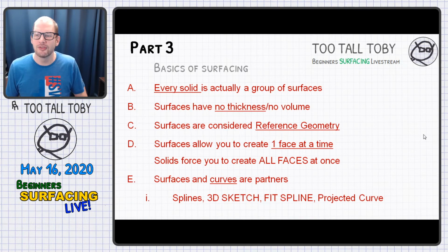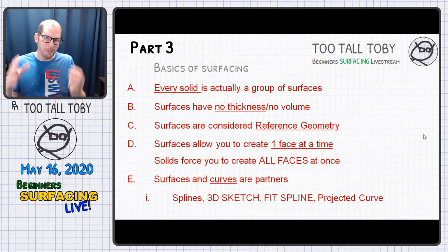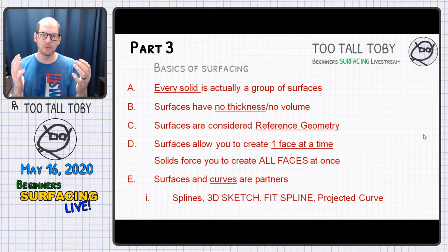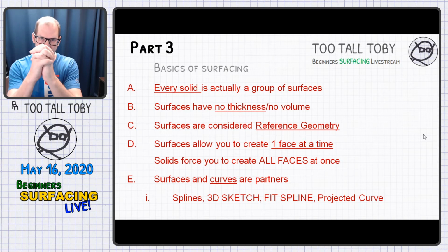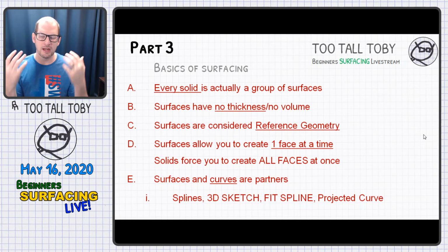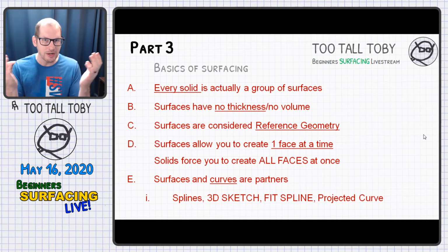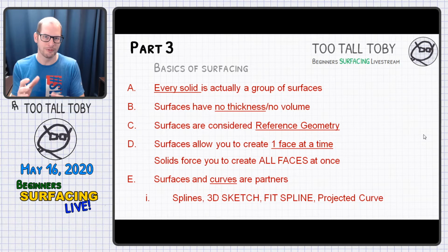And now finally, surfaces and curves are partners. So splines, 3D sketches, fit splines, projected curves. These are all tools that will go hand in hand with your surfacing journey. So if you're going to learn a lot about surfacing, start looking at videos and tips and tricks on how to use splines better, how to use 3D sketch, how to use fit spline. What is fit spline? How do we use that? How do we do projected curves? These are really important tools that all hardcore surfacing users are familiar with.